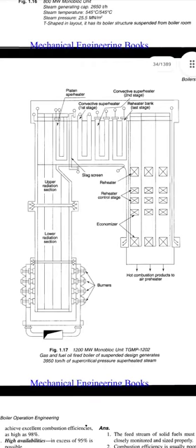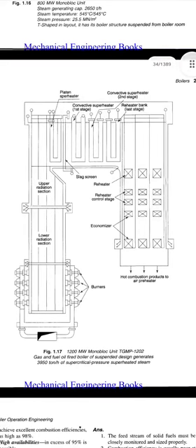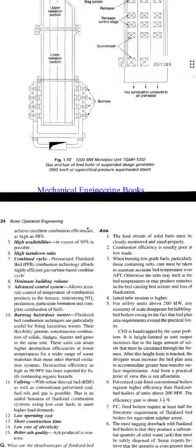After that, the flue gas goes through the reheater control stage, economizer. Then hot combustion products go to the air preheater. So in both diagrams, air preheaters are not shown. In between the platen superheater and convective superheater first stage, a slag screen is also there.